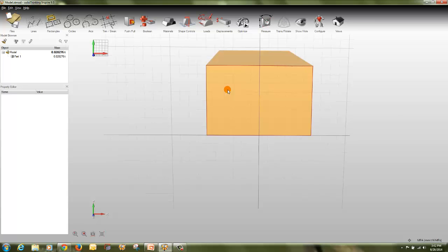Once you click it you can see 4 or 5 options here. So I'll explain what these icons are for. The first icon is sketch on a new part. This allows you to create a new part before you start sketching. Any existing sketch curve will be imprinted onto the current part before the new one is created. Now the second one is move current sketch to a new part. This allows you to retroactively move your current sketch to a new part.